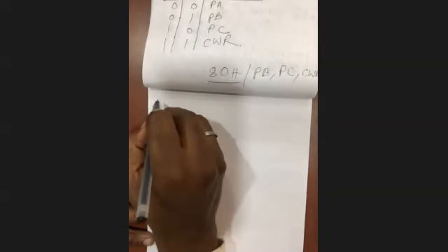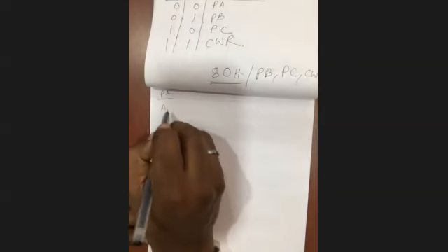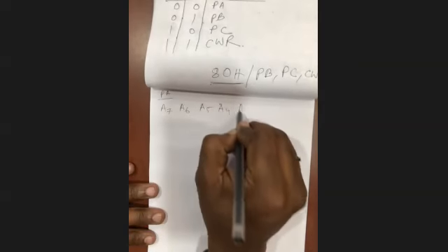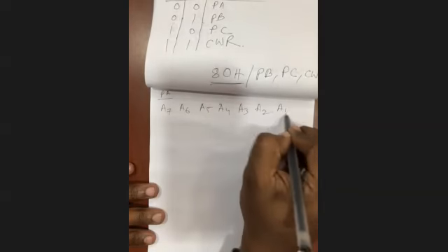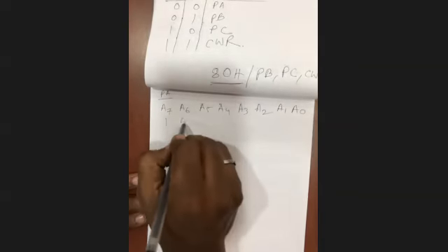First, write down the address of port A. Make it a heading. After that, write A7, A6, A5, A4, A3, A2, A1, A0. Then convert the 80 into this pattern: 1 0 0 0 0 0 0 0. Is it clear? Just 80 converting to binary.